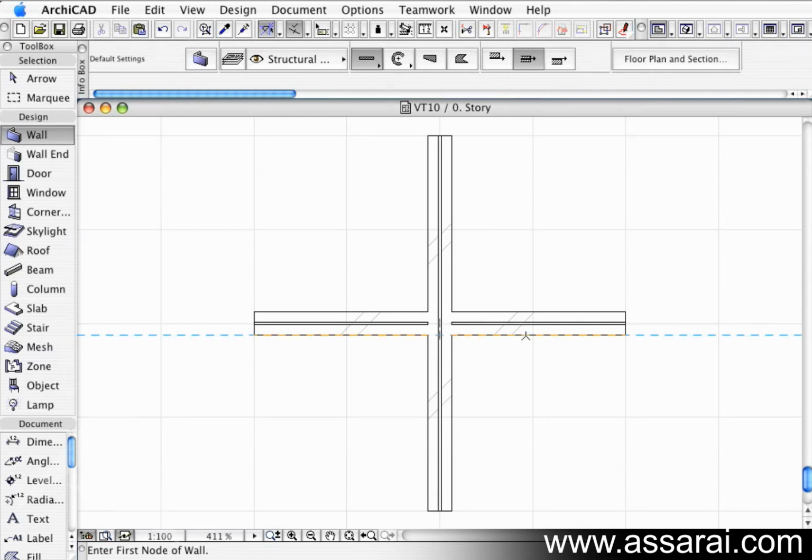so it's displayed slightly different. And just as a side note, walls will always have an even priority. You can't give them an odd priority, and beams will always have an odd priority. If I wanted to display this differently, for example, if I wanted this cavity to match up with this cavity, we just have to match the priorities of that particular skin in that composite.